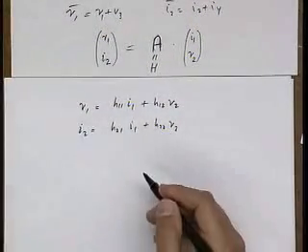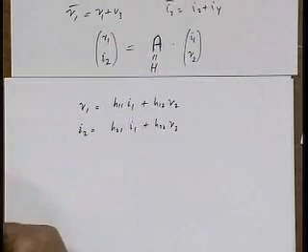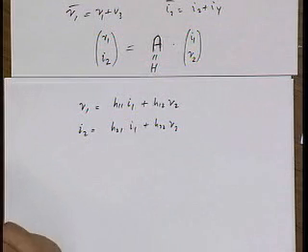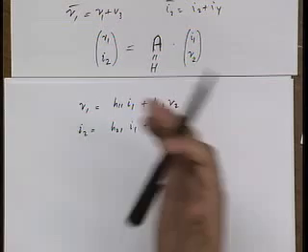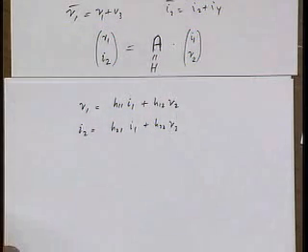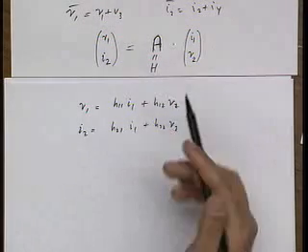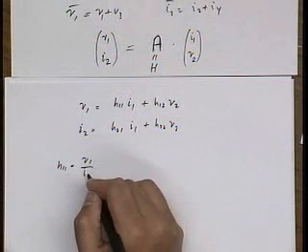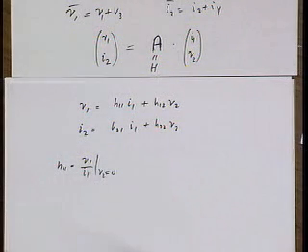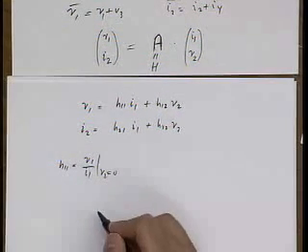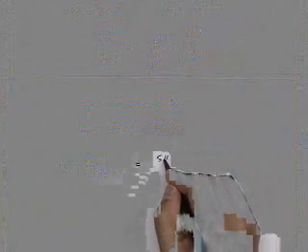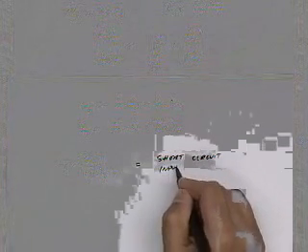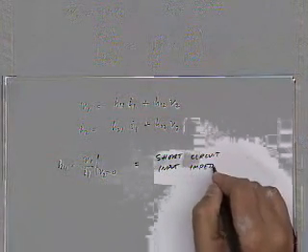So whenever, let's say you're on a take-home final exam, and so you have leisure, but you also want to get the right answer, and let's say it's closed note. So you've forgotten what the hybrid parameters are. Just write it down, and it's very obvious. H11 is just V1 over I1 when V2 is equal to 0. Well, that's a ratio of voltage to current. That means it's the short circuit input impedance.